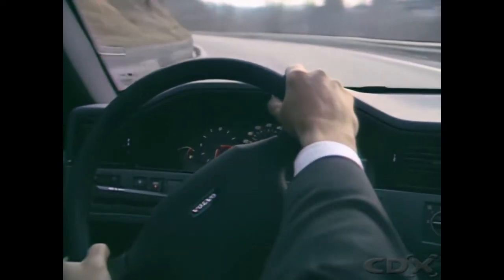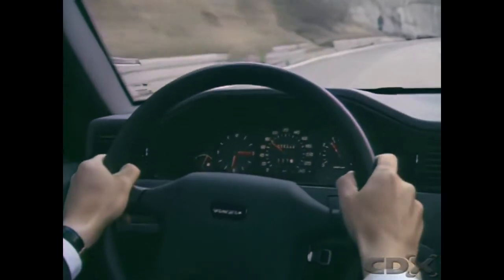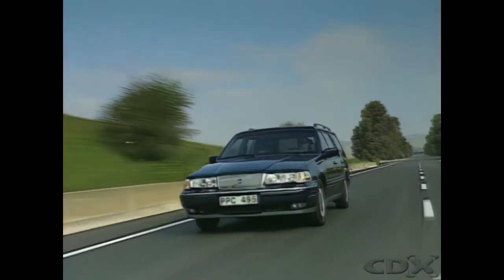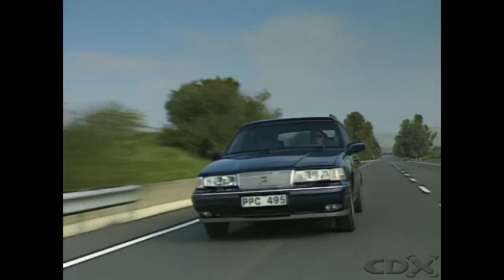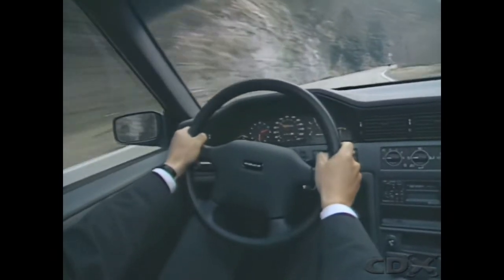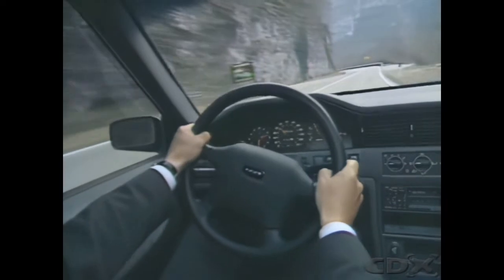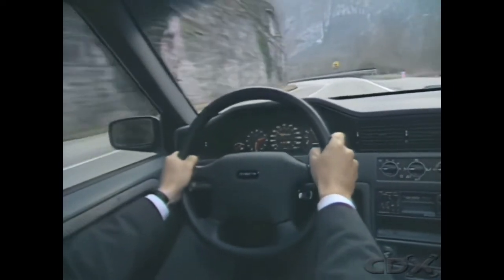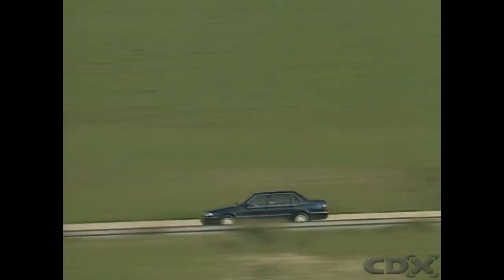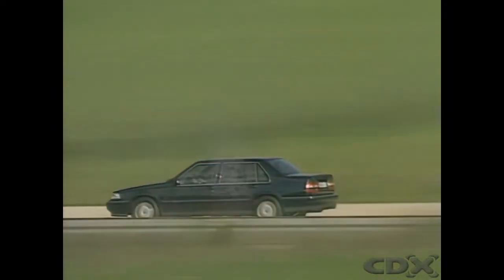Most cars have positive caster because it makes it easier to travel in a straight line with minimal driver action. But as positive caster increases, more and more effort is needed to turn the steering wheel. A small amount of negative caster reduces the steering effort needed at low speeds, but can make a vehicle wander at high speeds. In all cases, the manufacturer's specification should be followed.